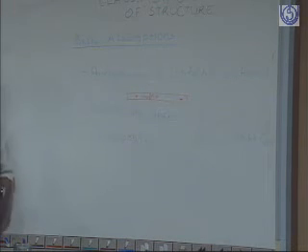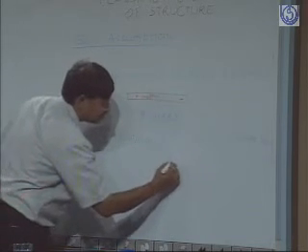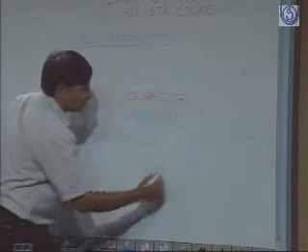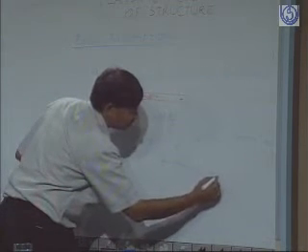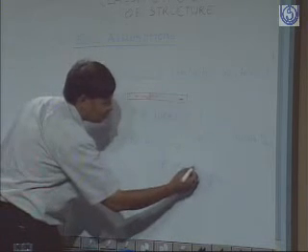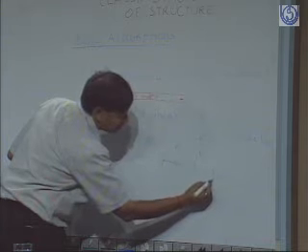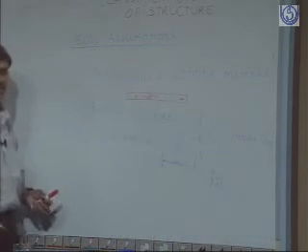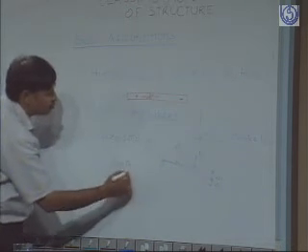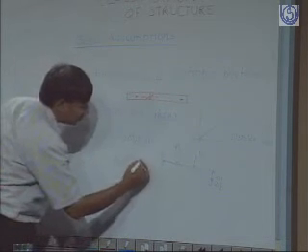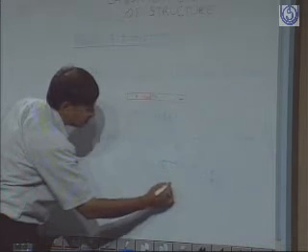It means that if you apply a load, say on any structure, if you apply load P1 and a deformation of delta 1 takes place here, again you apply a load P2 here, and because of this further delta 2 deformation takes place, then it means that if you apply a load P1 plus P2, then the deformation should be delta 1 plus delta 2.